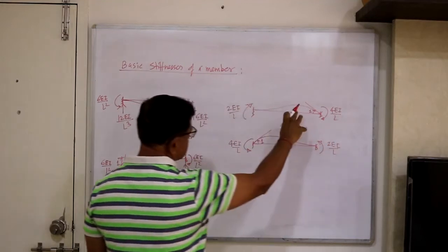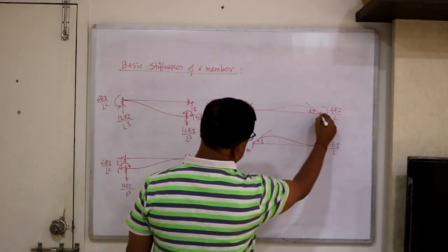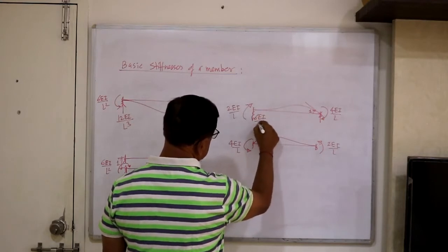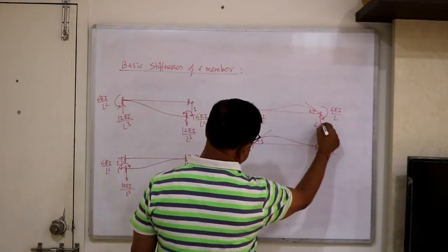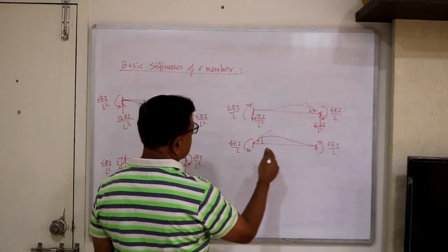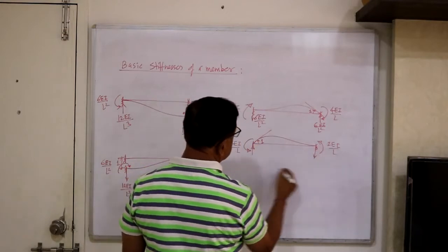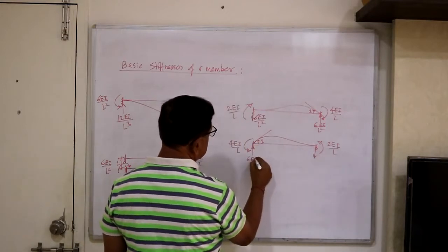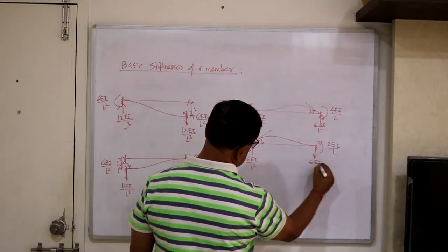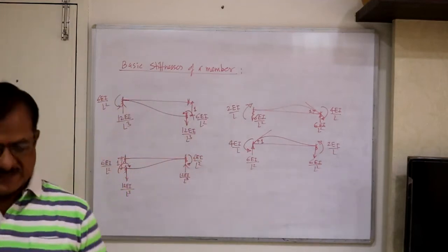And then, knowing this is an anti-clockwise moment, the reactions form a clockwise couple. This reaction is downward, this reaction is upward, this is 6EI/L² and this is 6EI/L². Similarly, for the other case, the reactions form a clockwise couple, 6EI/L² and 6EI/L². So these are called basic stiffnesses.